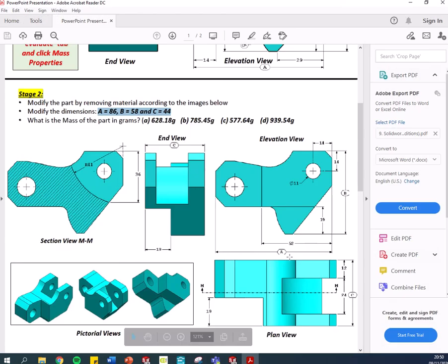Okay, nearly there. Next thing I will do is this swept cut here. Now this swept cut, we can see, we have to look for it here. So what I'm going to do is, let me see, I have to create a sketch plane to do this. So it's a radius 41 arc, and the center point is in line with this point here, and we have